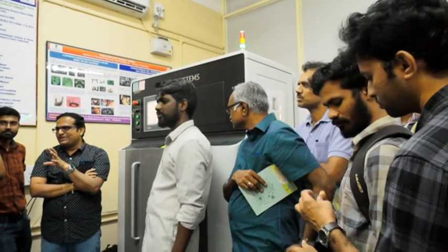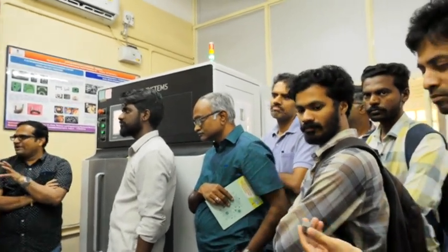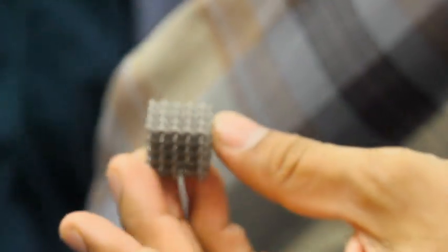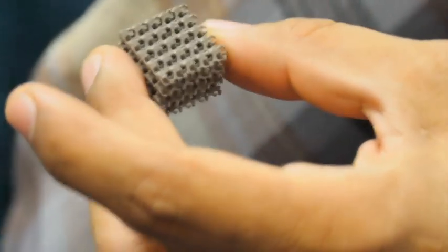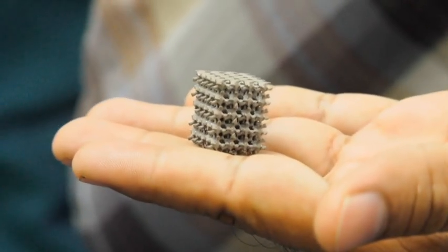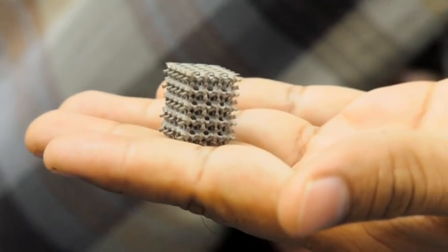But here there won't be any furnace treatment. It is a full melting technique. We are not doing any post processing in order to improve the density. It is a full melting process. But sintering, we need to do some furnace treatment in order to get 100% dense. Mostly that is the difference. Even for polymers and metals, some kind of binder, yeah, binder, they will mix with the powder, but it's a full melting process.